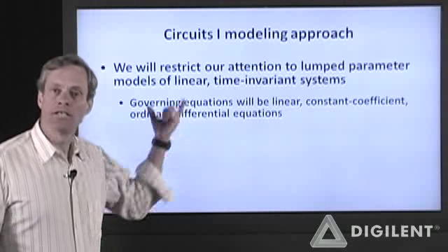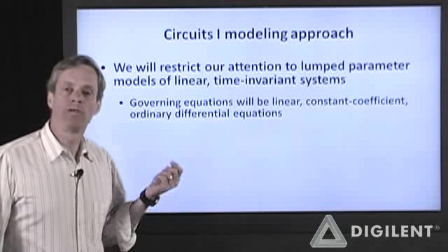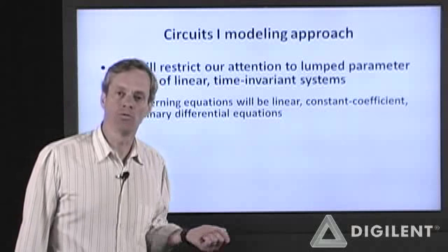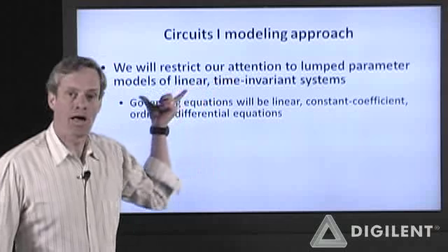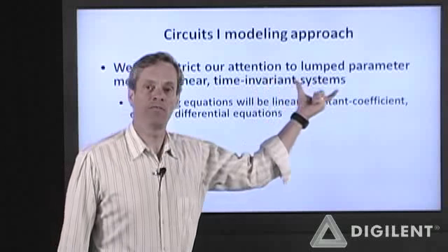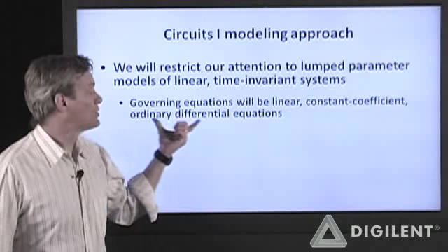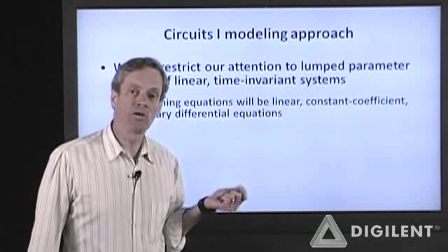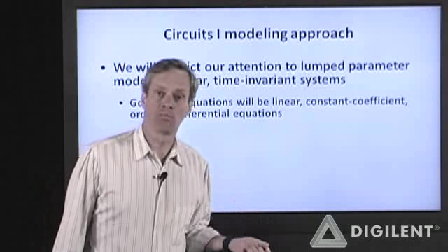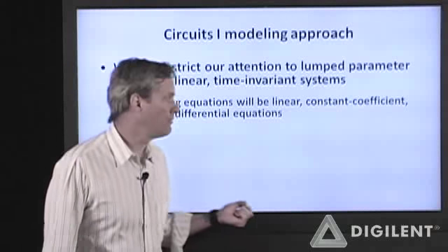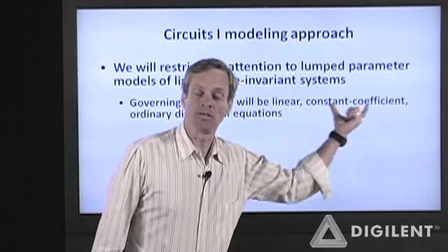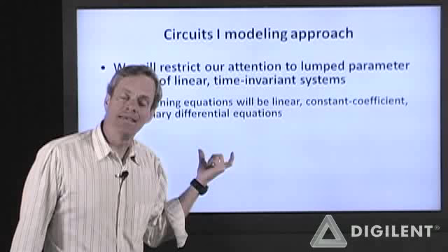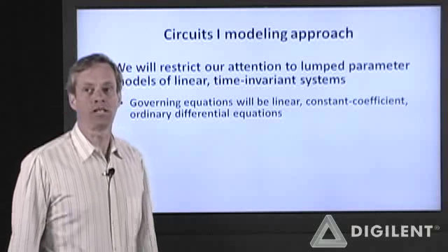In this class, in Electrical Circuits 1, we will restrict the category of models that we will be creating. We're only going to worry about lumped parameter models of linear time-invariant systems. So the governing equations that we create will be either algebraic equations with constant coefficients or linear differential equations with constant coefficients. We're doing the easiest possible case in this class.